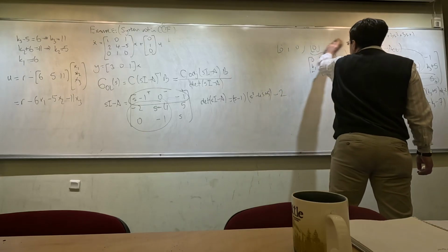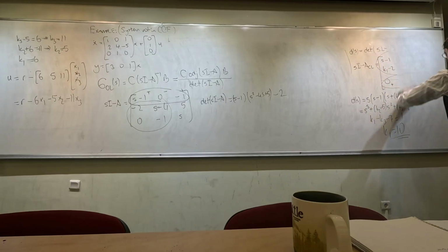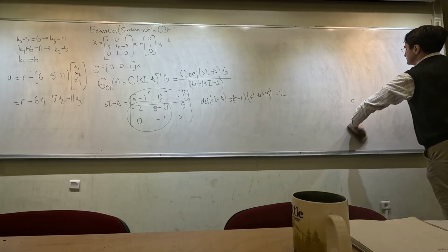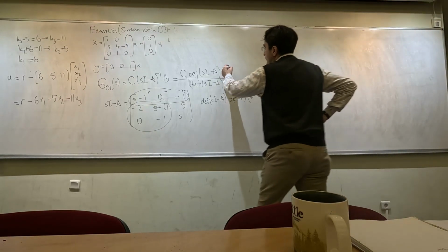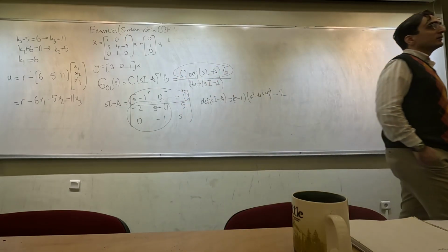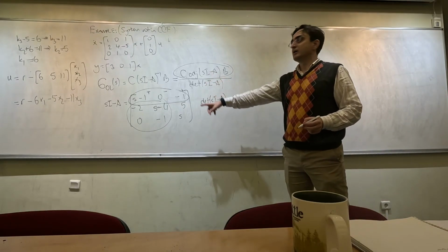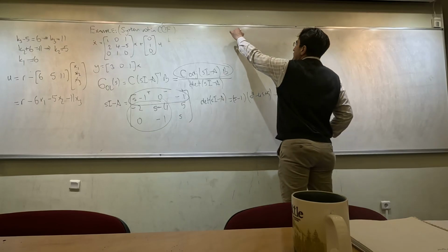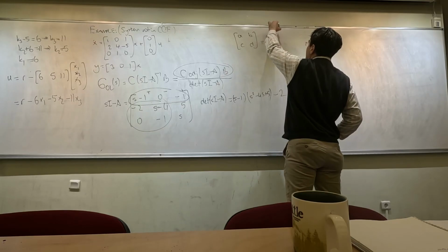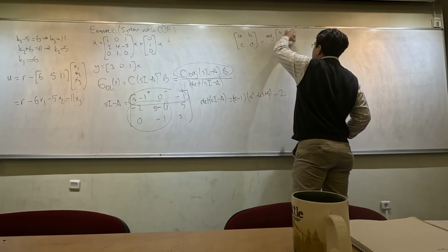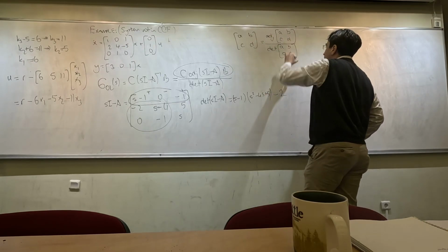Well, denominator is, finding the numerator is more problematic here. So here, let us try to find the numerator. Okay. When I try to find the numerator, I need to calculate SI minus A, the adjugate matrix. So if you would like to calculate the inverse of such a matrix, this is ABCD. It is adjugate of ABCD divided by the determinant of ABCD. Okay, that is the inverse of.